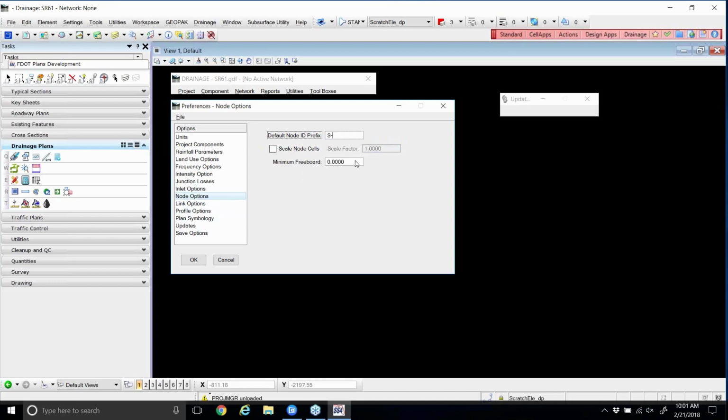And then it also has a minimum freeboard, which you'll usually see as 1 foot even, but this is going to be 1.125. And the reason for that is it's including the little drop on the gutter section. So you'll see there's a big gray note here right in the middle of page 324. They're adding the 1.5 inch gutter depression, that's where they get the 0.125 from. So that's why it's not just an even 1.